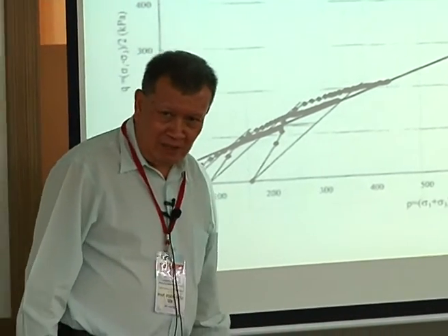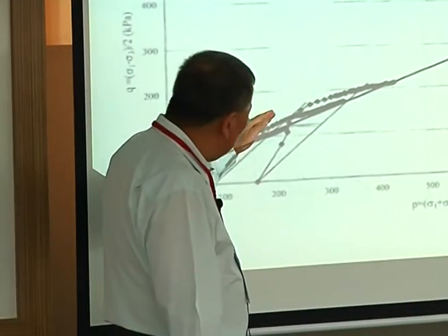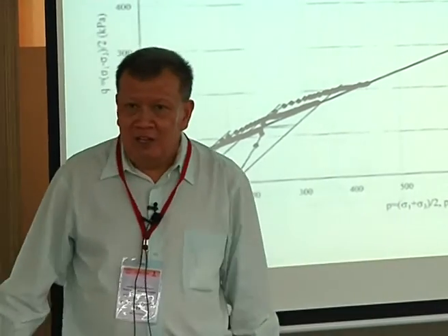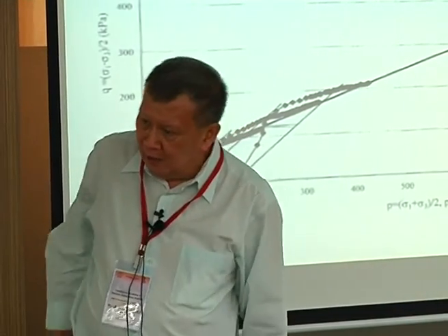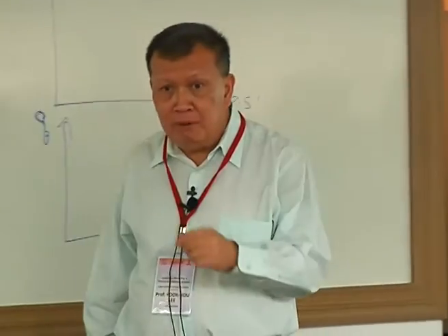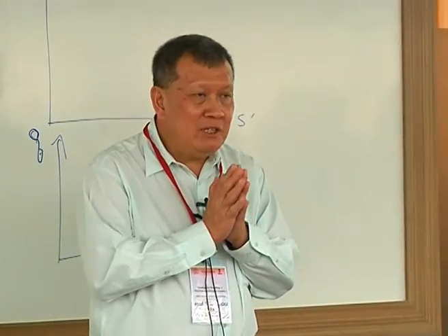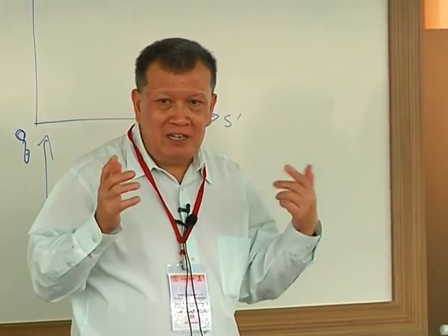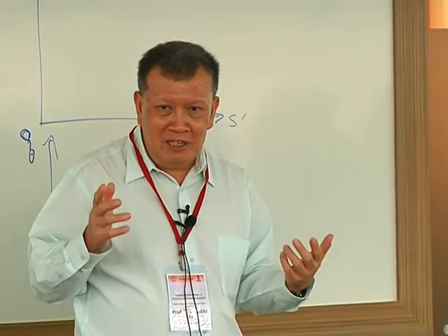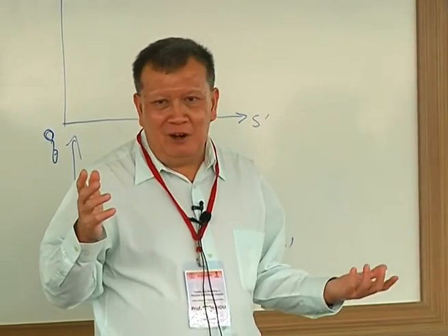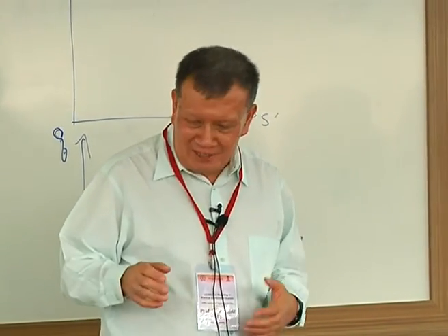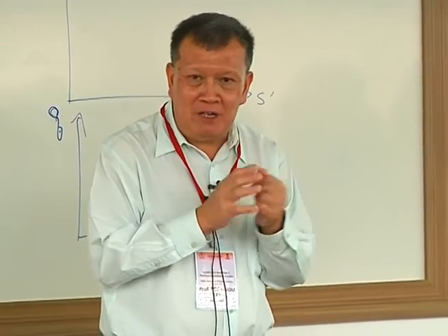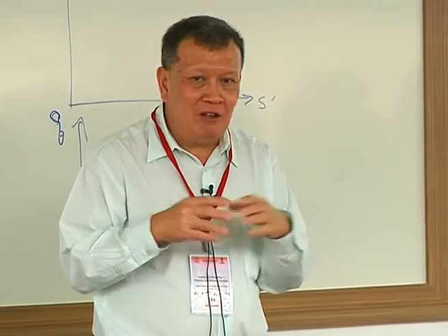But it is not unreasonable sometimes to expect real soil to shoot above the yield surface. Although we say the Mohr Coulomb model should not allow the soil to go past, the soil doesn't understand Mohr Coulomb. It only understands its own behavior, so it will go its own way. Sometimes you'll get a bit of an accident. This is part and parcel of the imperfection of soil models, and it's not just Mohr Coulomb.